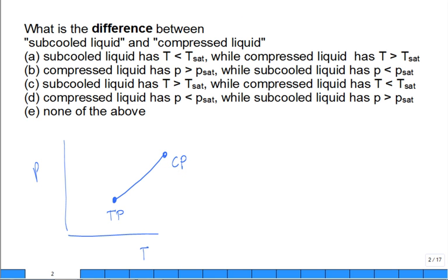And if our pressure is greater than along this line, we have the saturation pressure for a given temperature, right? So if I said, okay, here's this temperature right here, you could come up, you get the saturation pressure. If the pressure is above, what do you know? Is it liquid or vapor if the pressure is above that line? It's liquid. And if it's below, vapor. If it's right on it, guess what? It's a two-phase liquid-vapor mixture. Or it's in some saturated liquid or saturated vapor or two-phase liquid-vapor mixture state.